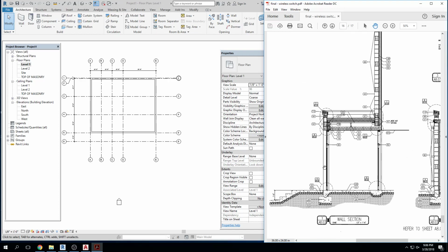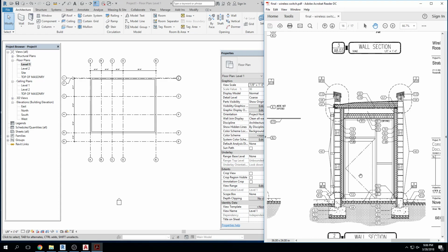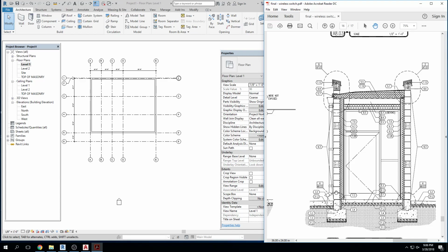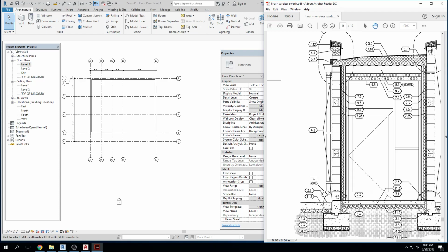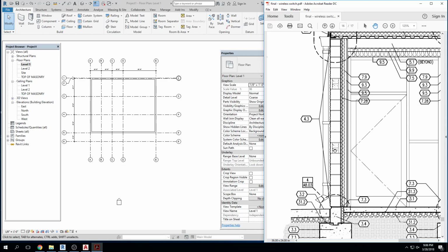So we're going to be counters. We're going to start counting, right? When you start working, you start counting a lot of bricks and a lot of block and a lot of different things you know the dimension of. So in general, I know that a block is going to be 7 5/8 with a 3/8 inch joint, so we can say confidently that these are going to be 8 inches tall, right? So I have 1, 2, 3, 4, 5, 6. We have 16.